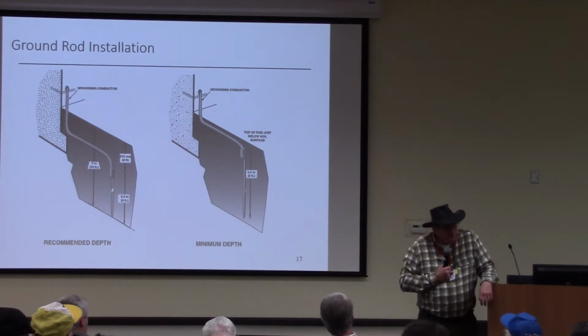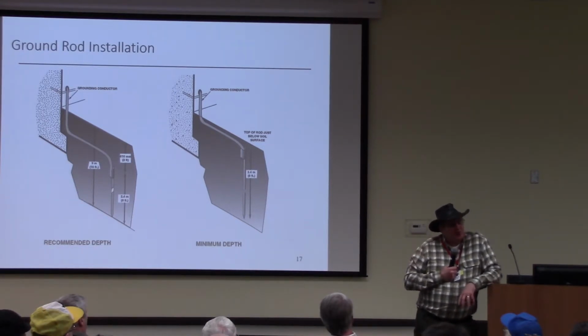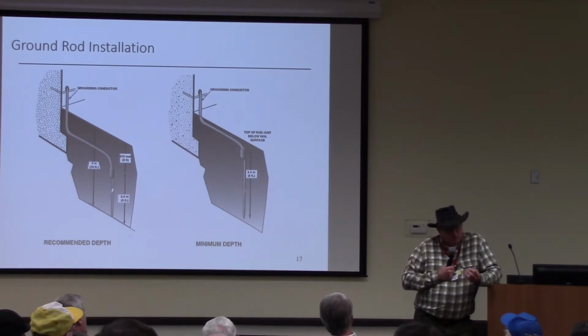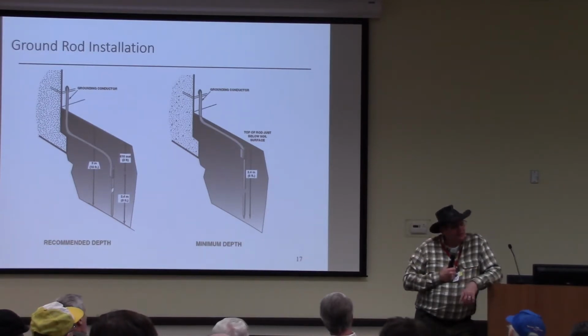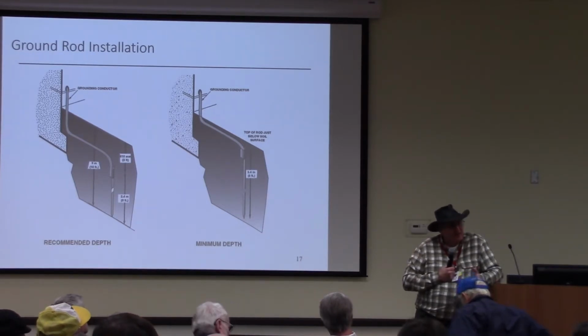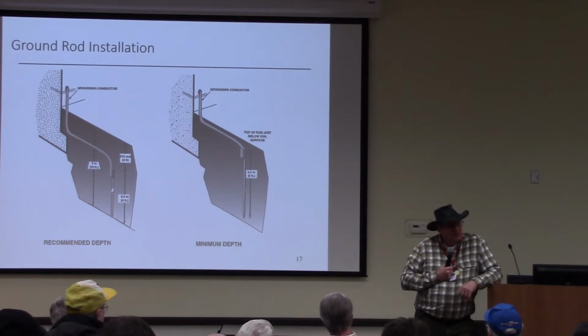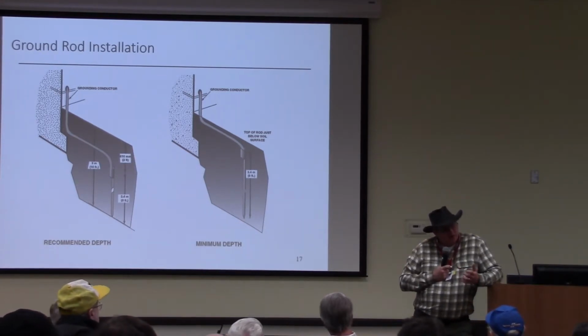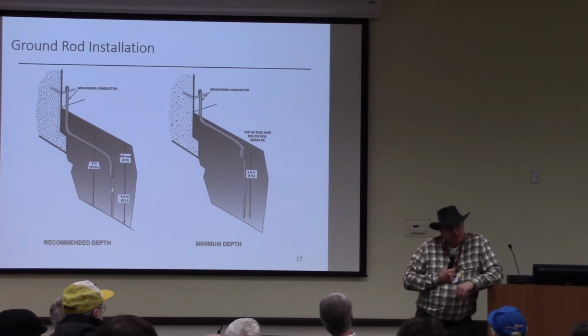With a typical strike, no. But each time it is struck, it does have a little bit of molten metal, a little bit of melting at the tips. So as the device is activated more and more, those tips melt, therefore the gap gets wider, therefore the voltage breakdown point gets greater. So they have a finite life.